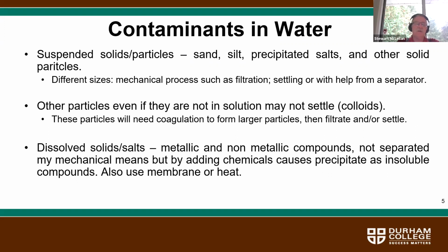So I did give an example previously of industrial wastewater treatment plants, where once they precipitate all the dissolved solids, they're generally there in very, very small particles, typically colloids, and they need to add a coagulant or a flocculant to get those very fine particles to clump together to form larger particles, which can then be filtered and settled out of the water.